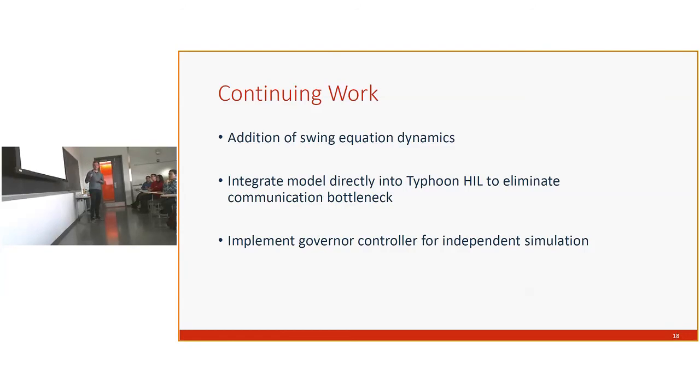We would also like to integrate the model directly into the Typhoon HIL. Right now, we have a separate computer running OpenDSS. It communicates over the network to the HIL and then back, which does add some significant delay to the simulations. We know that it is possible to implement OpenDSS on the Typhoon HIL. That's just something we need to do. So that will eliminate our communications bottleneck.